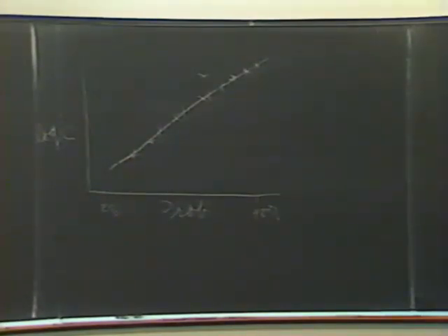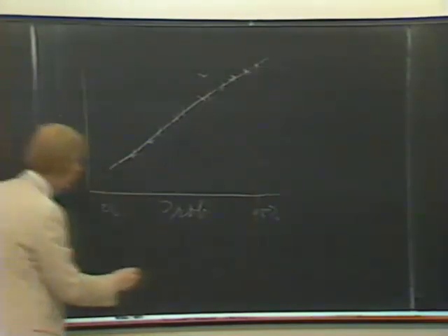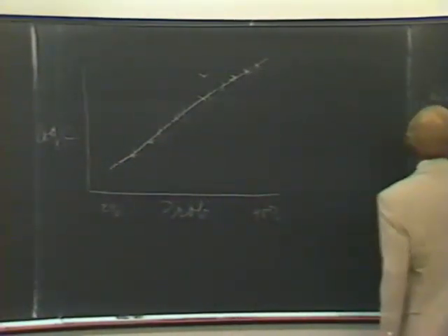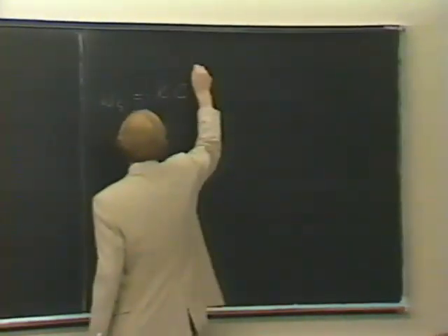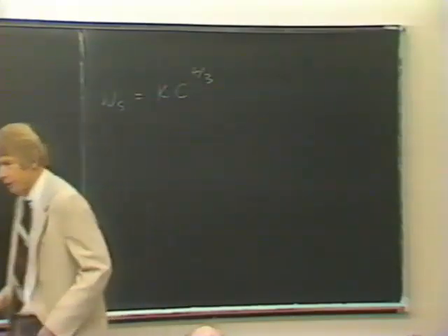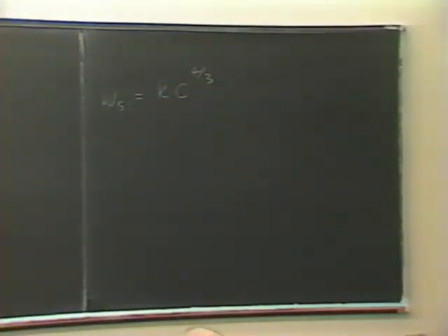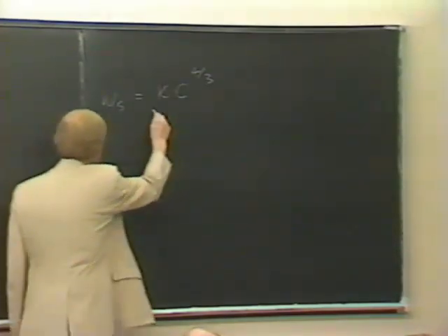See, there are a couple other points I wanted to... Oh yeah, the last one is the settling velocity. The difficulty is that we aren't really able to get settling velocities in a reliable way. The way that we've been talking about, W sub s equal to some constant times the concentration to the 4/3 power, works pretty well in systems where breakup isn't a process. That is, where aggregates have formed to the point where repeated collisions are infrequent. And that might be a case in, let's say, marshland.